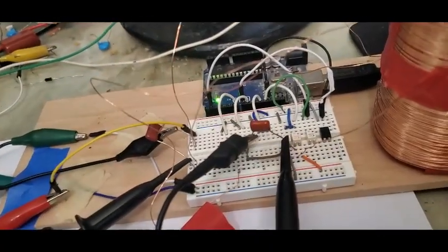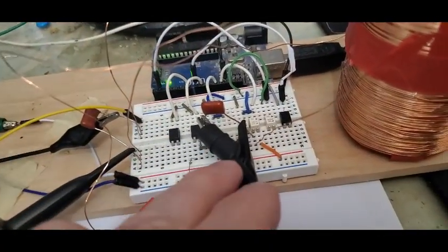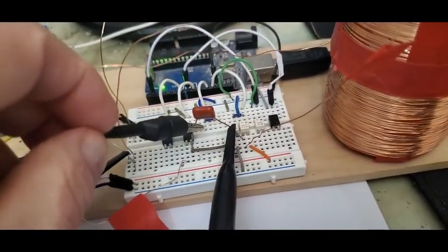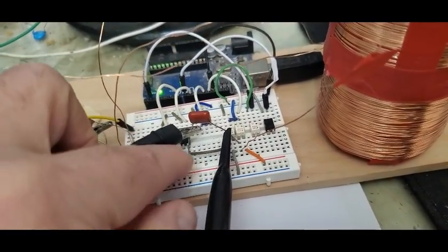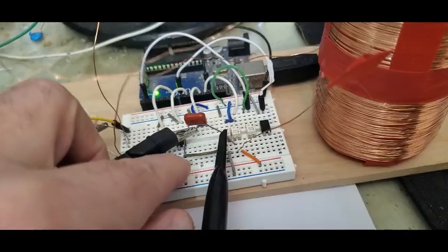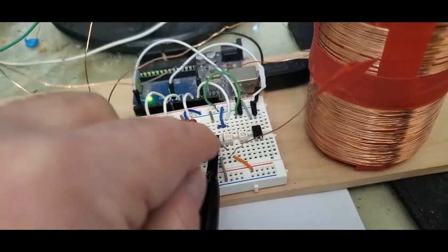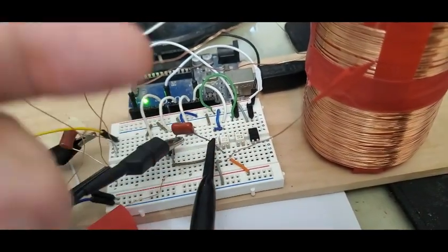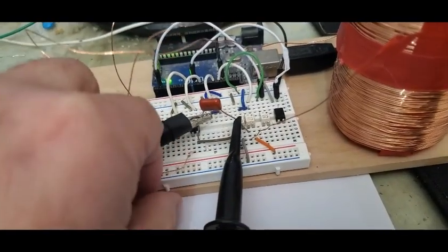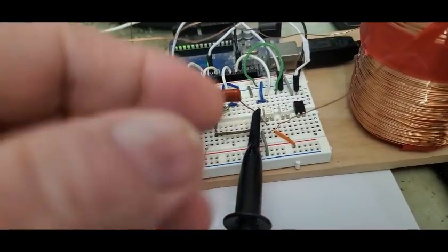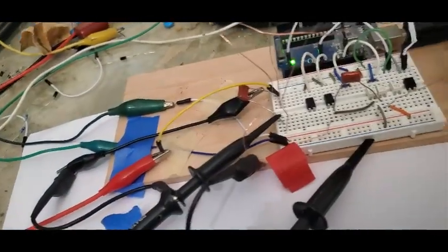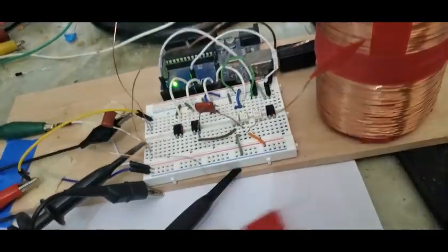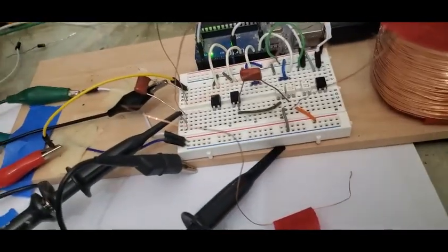The other interesting thing is that at that point this isn't connected to there, so it's just the cap charging up and this one end of the wire sitting out there. So I was thinking, well, maybe you get rid of this. Now, of course, you still need to be able to discharge the cap. But what happens if we pull this line out and just put a short across the cap there?